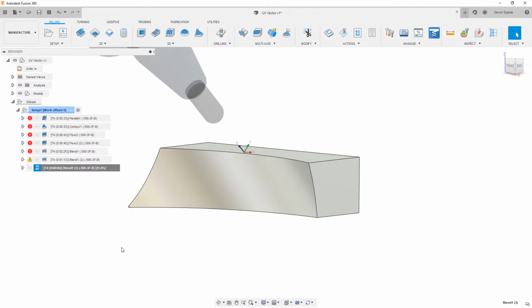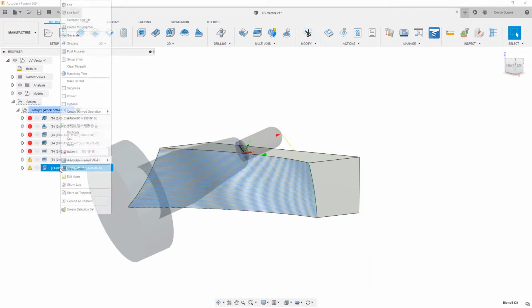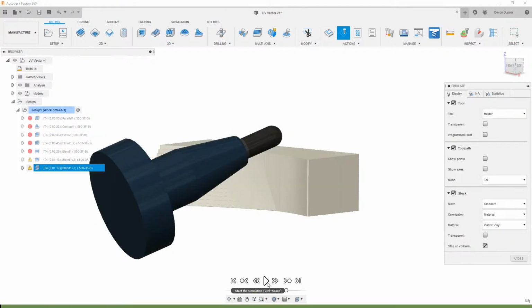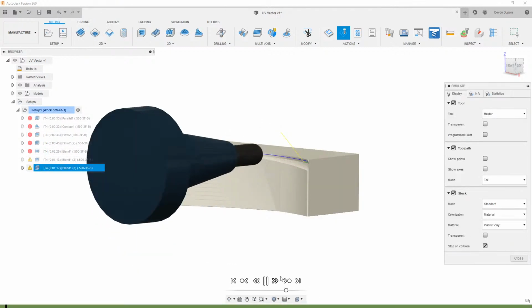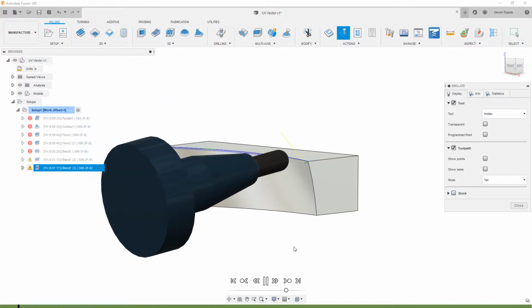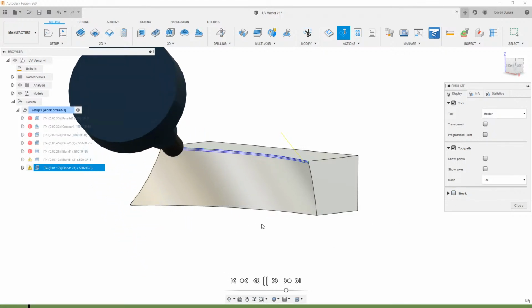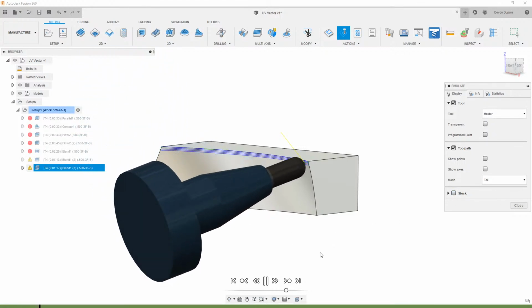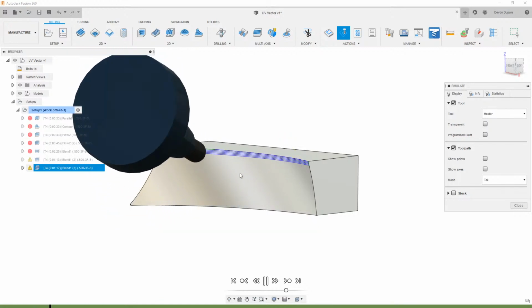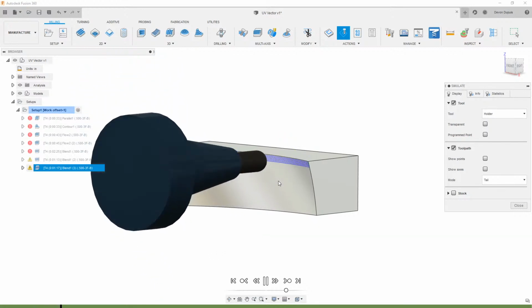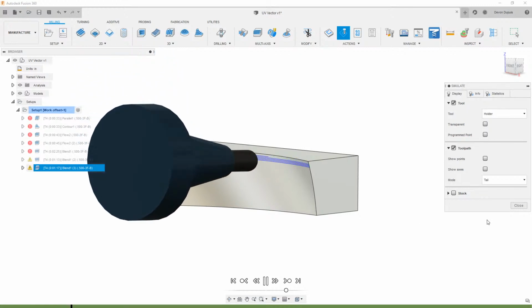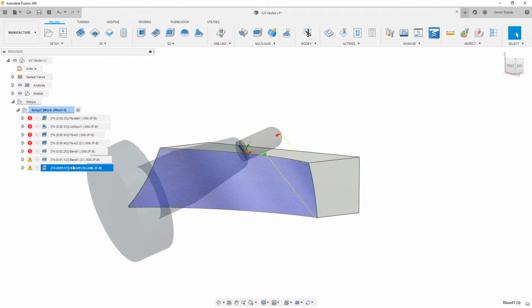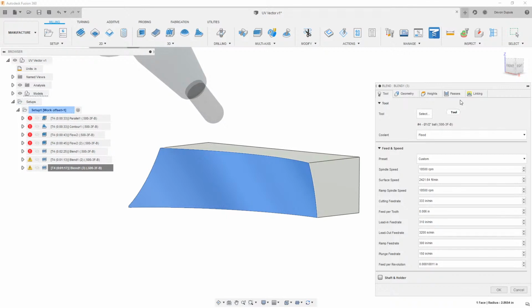But there is a problem with blend at the moment. So if we right click on this and we hit simulate, we'll see this is going to go both ways, kind of like I told it. And we'll turn this off just for performance. So this is going back and forth really nicely. But on a mold part or something that needed to be smooth with a nice look, I generally wouldn't want to go both directions here. So what we would do is come over here to blend, and we would just turn this to be one way.